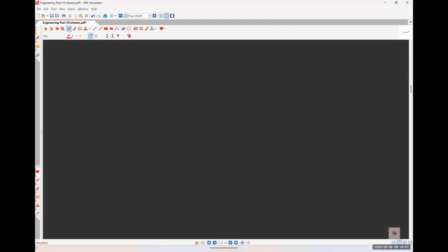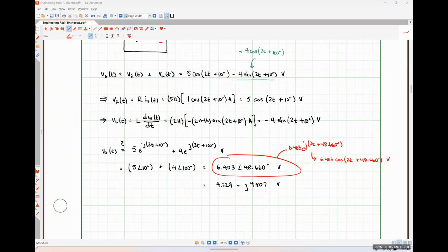So we can go from any two sinusoidal signals added together to a single sinusoidal signal by converting both signals to cosine functions and then just converting them into a polar form complex number and then doing whatever math we need. But sometimes your homework asks you to express that combination of signals as something cosine omega t plus something sine omega t, where you don't have any phase angles whatsoever to deal with. That's where this rectangular form comes in, okay?